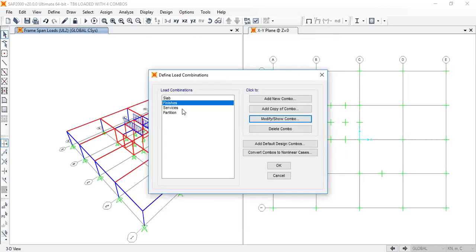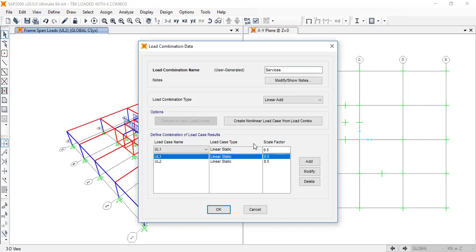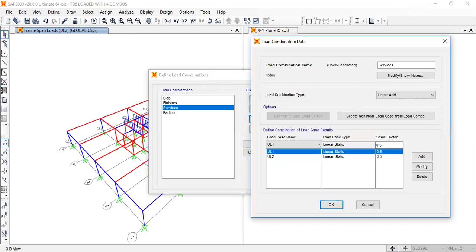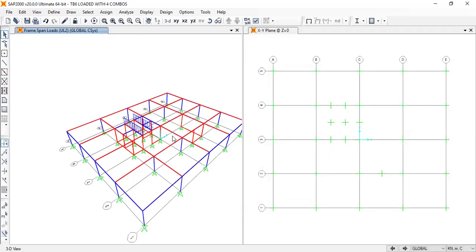So, and for the services, you will use services 0.5, right? 0.5 and 0.5, but you will see in this lift area, mostly services will be concentrated, so you need to be aware, right? In this middle core area, they will have different services, washrooms and other things, right? So you can be aware, and apply some different unit loadings to compensate for that.